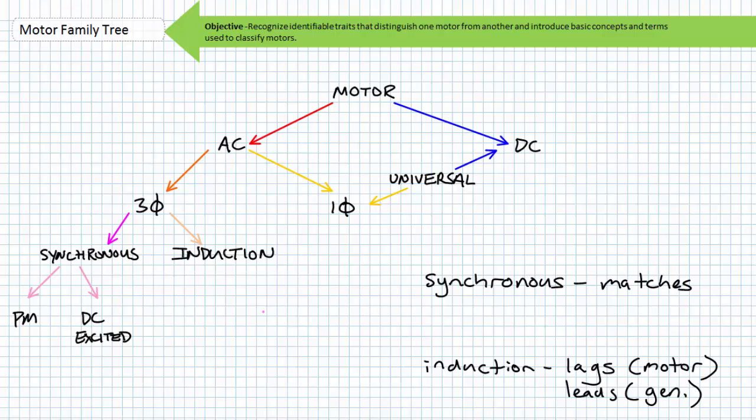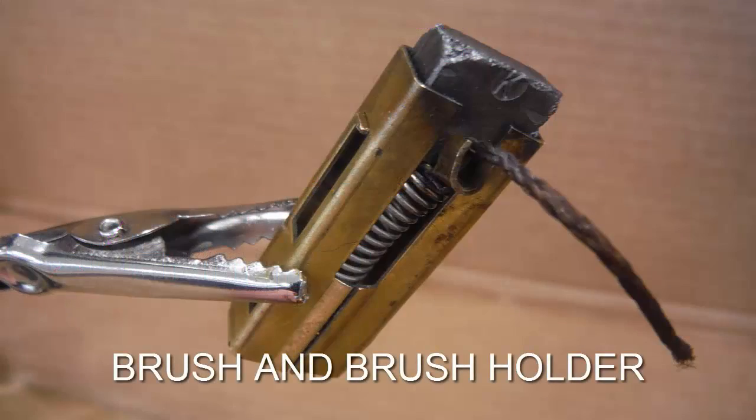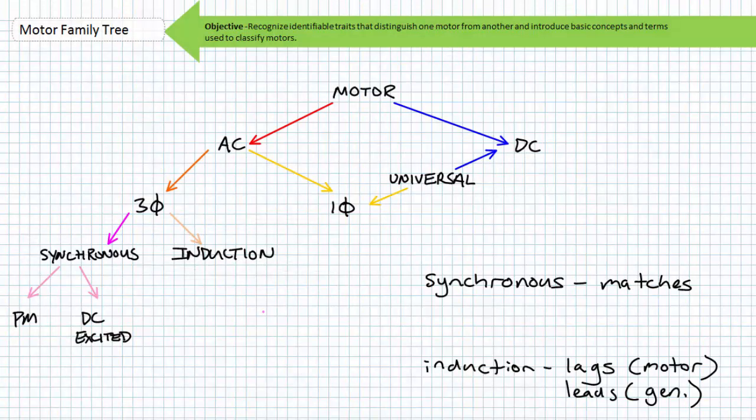Electrical slip rings ideally don't leak electron juice everywhere, but they're not maintenance-free by any means. The brush itself is a consumable. At a certain point in its lifespan of rubbing its head on a ring while a spring is pushing on its feet, it's going to get shorter and shorter and eventually cease to function. All those brush parts being rubbed off have to go somewhere, and they accumulate as an electrically conductive dust wherever it's the worst place to congregate. A large portion of low-level maintenance performed on motors and generators is simply replacing the brushes and cleaning out brush dust.